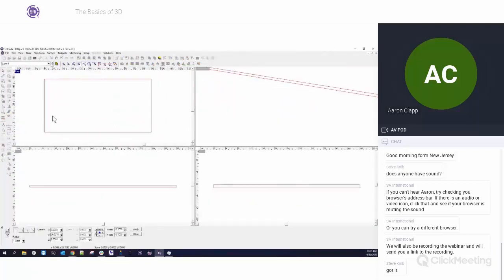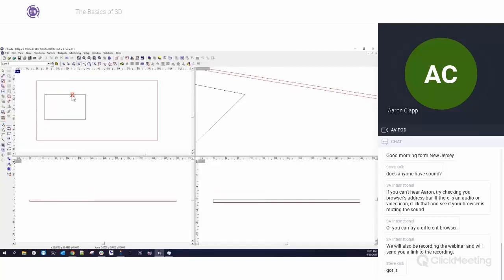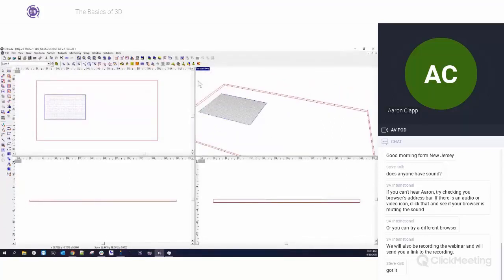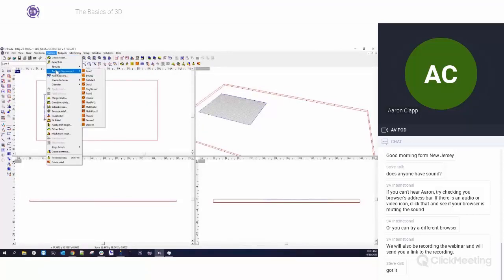We want to go over just briefly creating a texture. First of all, we've got to set up our base relief. So I'm going to say add flat relief, leave this at 0 and hit apply. So now I've got my flat zero thickness relief applied. I'm going to select my relief, go to surface, and now we can create some kind of a texture.